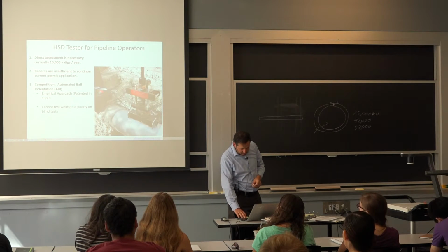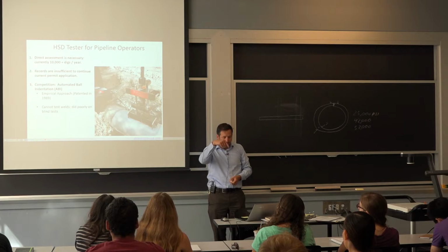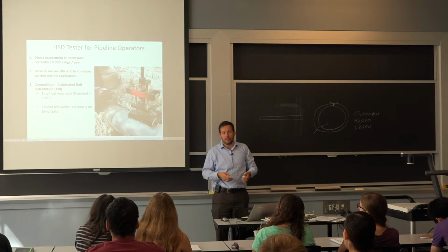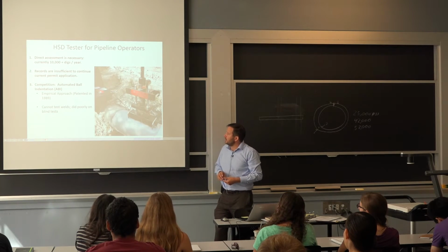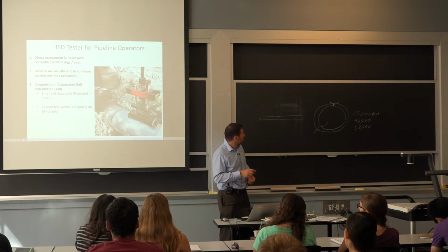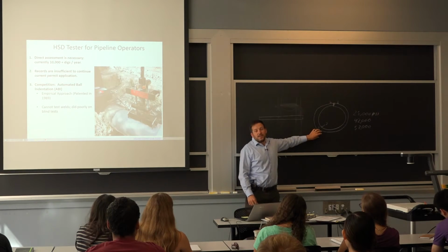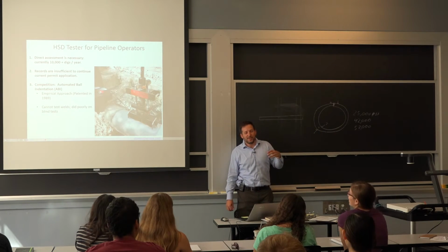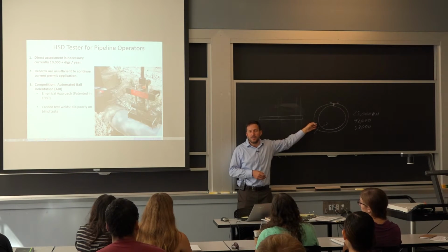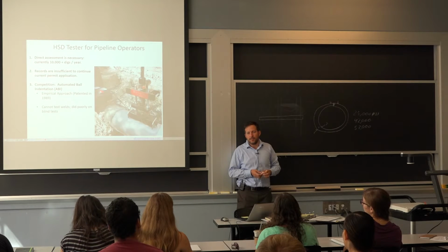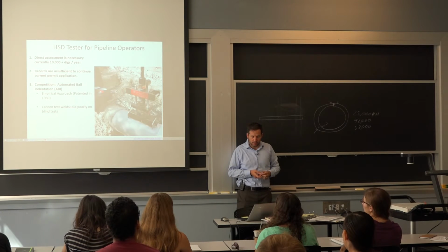The current alternate technology has been to do indentation, and that's possible. We can go over that. You can do a hardness test, but you don't collect as much information, and it's very empirical. And to tell you the truth, they haven't worked this issue. So we're trying to both have a better technology, but also have a better ability to back calculate the effect of strain hardening and microstructure gradation.